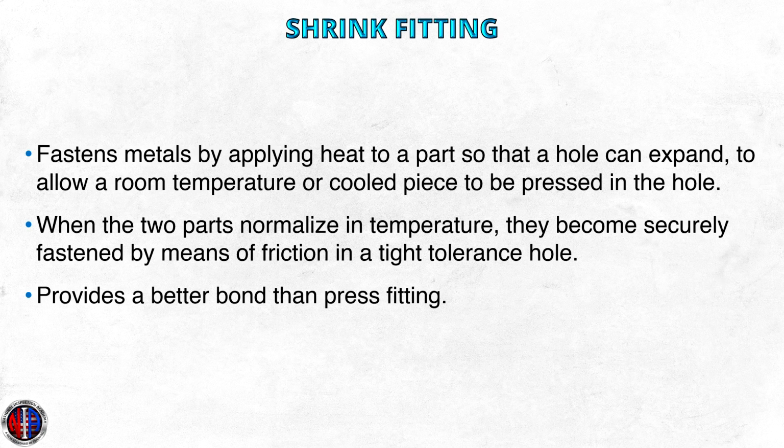Shrink fitting is another means of fastening metals by applying heat to a part so that a hole can expand to allow a room temperature or cooled piece to be pressed into the hole. When the two parts normalize in temperature, they become securely fastened by means of friction in a tight tolerance hole. If done correctly, shrink fitting provides a better bond than press fitting.